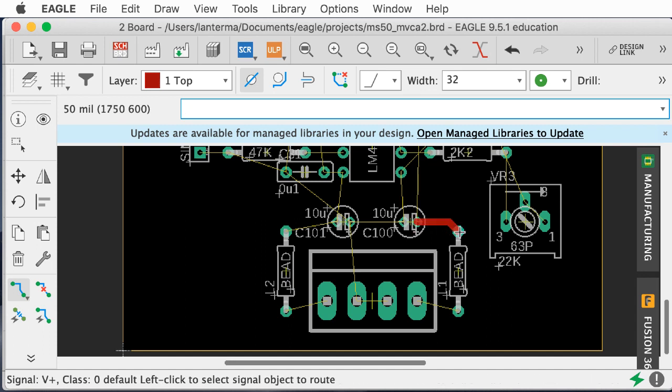Let's go with this. So I'm going to use red, which is the top layer now, to route the power. So I click on an air wire, and so I get together like that. If it's something like these capacitors where the pin isn't really on a nice grid, I like to click over on that side so it starts there and then ends somewhere else.